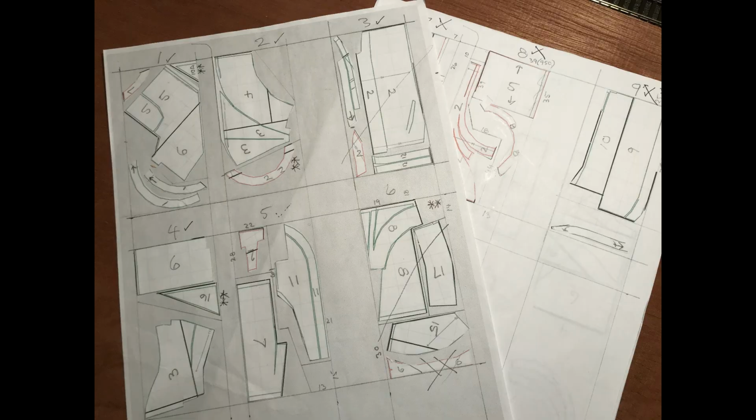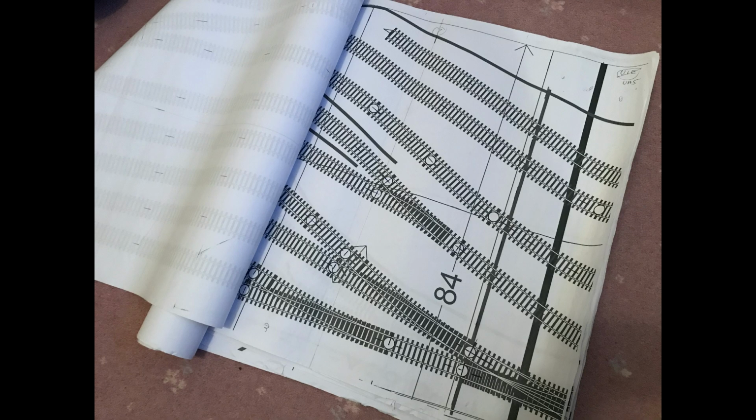I used a small scale plan to cut out the track bed shapes to work out the most efficient use of plywood. This still ended up using 10 8x4 sheets to provide all the track beds as well as backboards for electronics, etc. The full-size track plans were then pinned down on the 8x4 sheets of plywood in the appropriate location, making sure adjoining sheets were lined up, and the track plan and track bed boundaries traced through onto the plywood, which could then be cut out with a jigsaw and positioned on the baseboard framework.